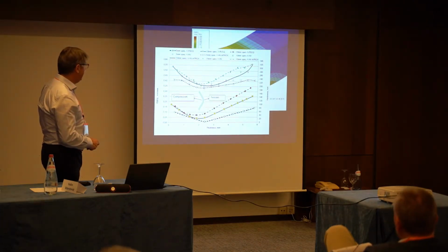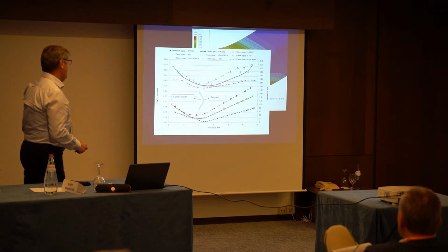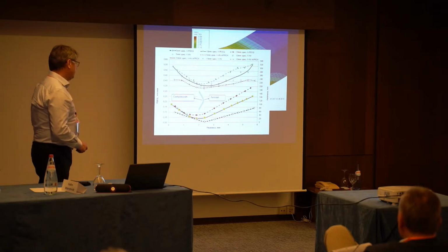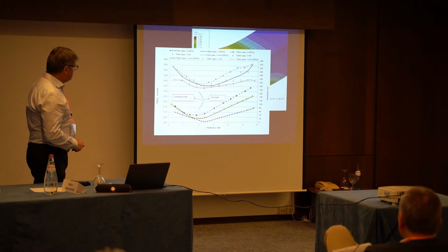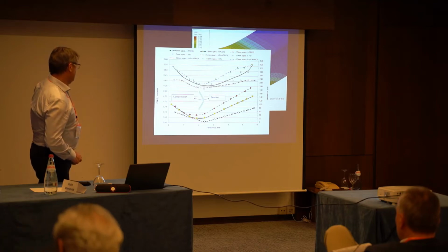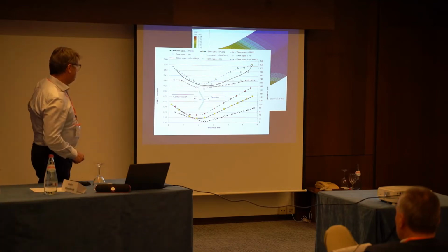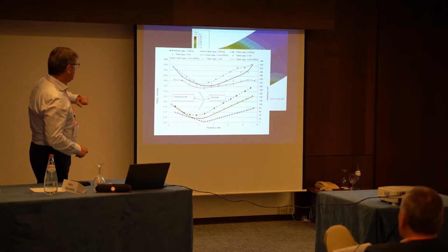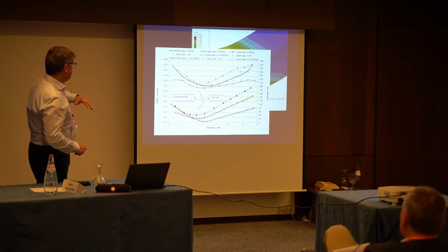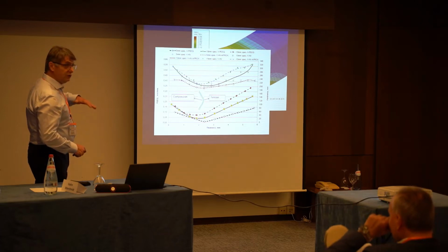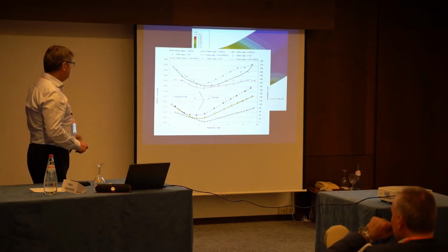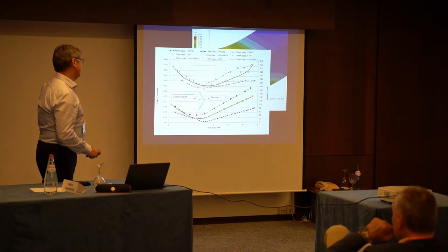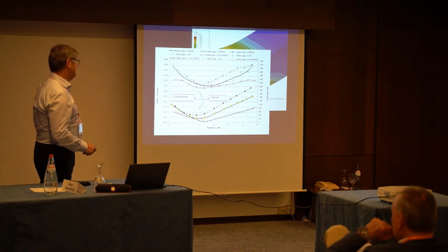And now what we got with our results is for 5 millimeters bending, 10 and 15 millimeters bending, and here you have the equivalent stress. You can see that this equivalent stress for numerical work is actually here. It depends, of course, how deep you go, 5, 10, or 15 millimeters, but we also have here the oscillation with hardness, which we get by measurement, and we can see how the hardness changes on this level.